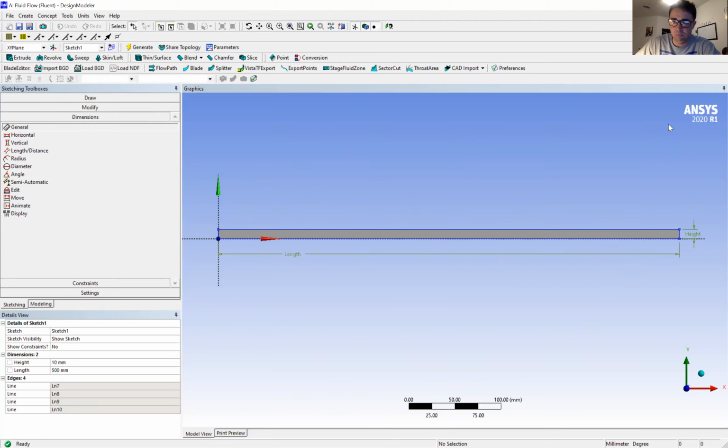I've done this before the video because it takes too long to do in the video, so I'm just showing you the process. But once that is completed, we went to our concept. We went to surfaces from sketches. We clicked that. We were able to essentially draw a box around the selected figure and put a face on that figure, so it has a solid surface.